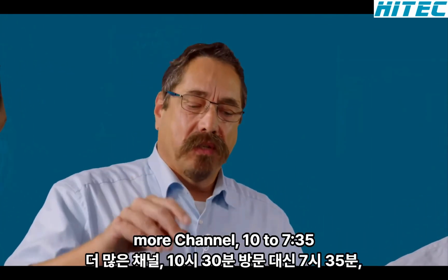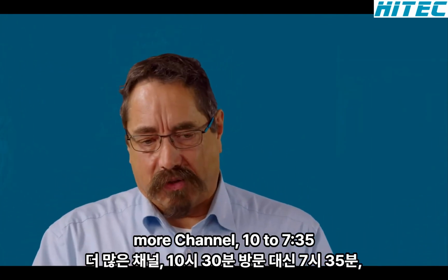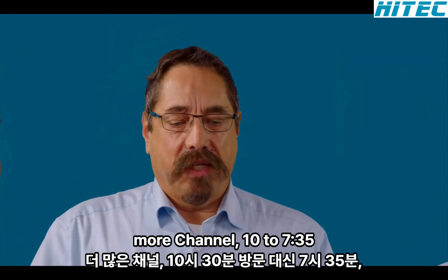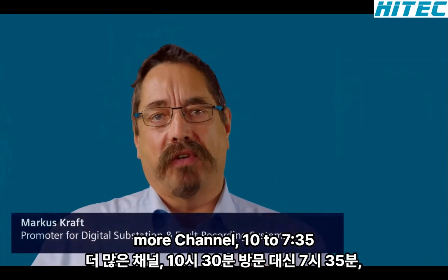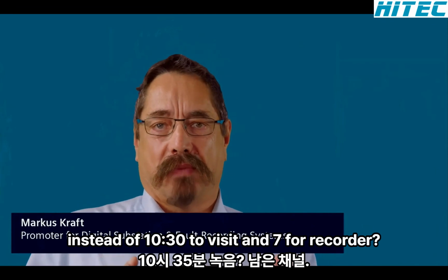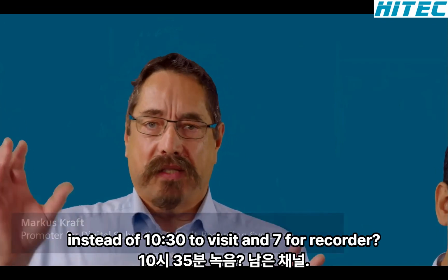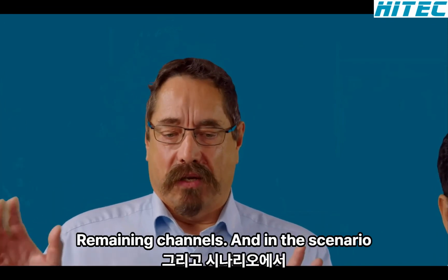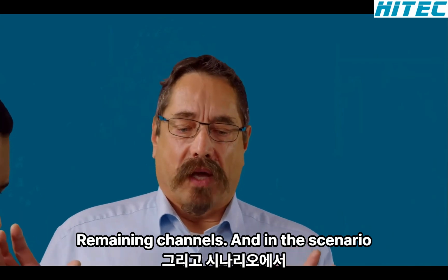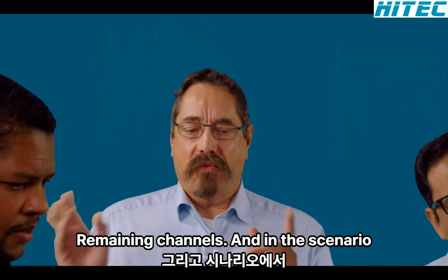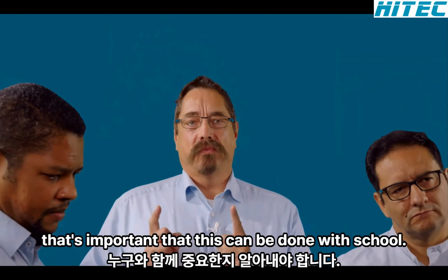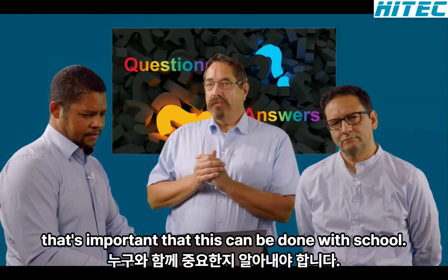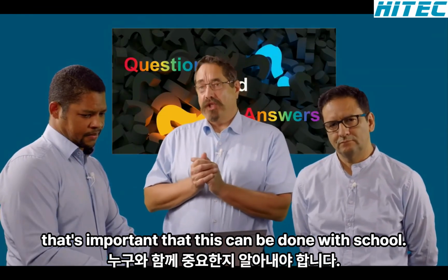Yes. And in this scenario, what these colleagues in the audience are asking is, when we need more channels in the 7K85 instead of the maximum 32 with the process bus, then we need a second fault recorder which takes care of the remaining channels. And in this scenario, we have to trigger both together. That's important. This can be done via Goose or via binary channel.